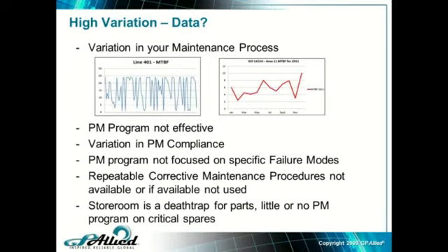Then repeatable corrective maintenance procedures not available, or if available, they're not used. And what I mean by that is step-by-step procedures with specifications, with standards that tells us how we do the work. And people say, well, I don't need those procedures because I've been performing maintenance for 30 years. I'm a skilled craftsman. Well, great. Can you remember everything that you did? No. It's not possible. Humans are full of error. So we have to put the procedures down. We have to develop procedures so we all do things the same way.